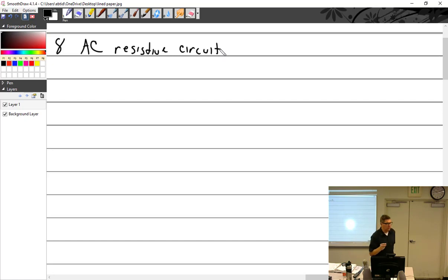So if you are working with AC and you take a voltmeter and you plug it in, it's going to say 110 or 120. We'll say 115. So you measure it, but then you take an oscilloscope and you put it on there and go, well, dang it, how come the oscilloscope says 169 and my voltmeter says 120? I'm totally lost, right? But are you lost? No.